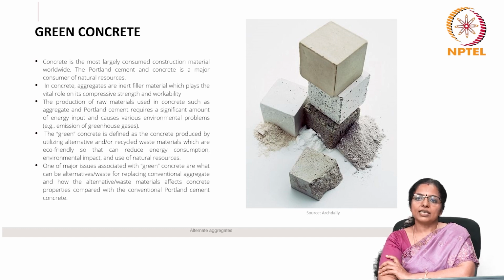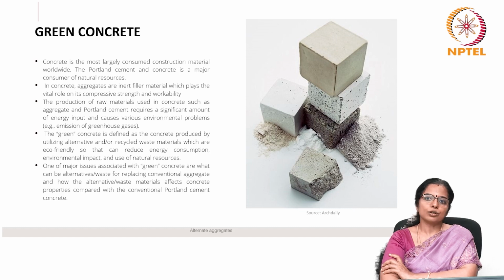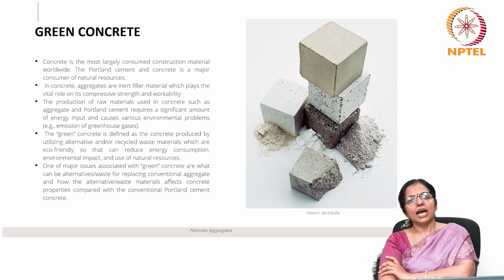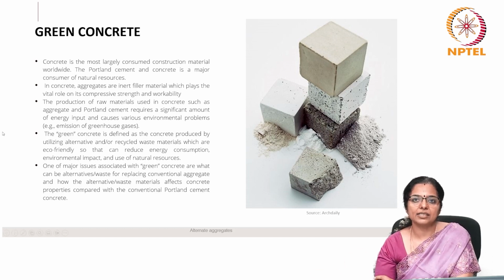Green concrete is defined as concrete produced by utilizing alternative and or recycled waste materials which are eco-friendly, so that they can reduce energy consumption, environmental impact and use of natural resources. One of the major issues associated with green concrete is what can be alternatives or waste for replacing conventional aggregate, and how the alternative or waste material affects the concrete properties as compared to conventional Portland cement concrete.